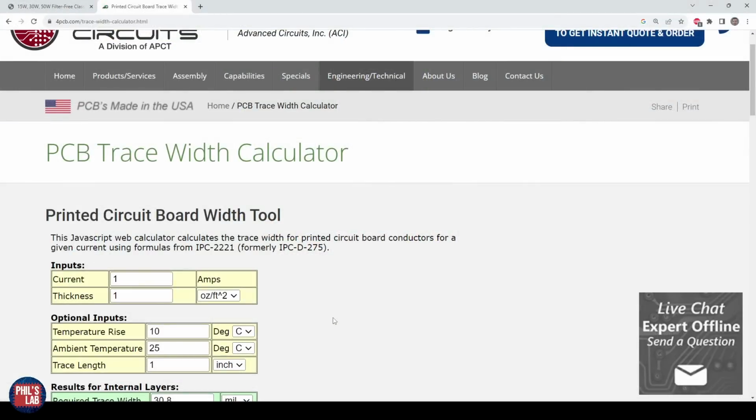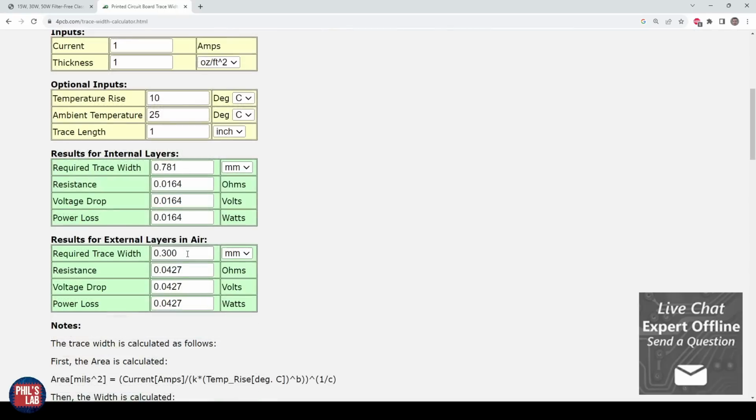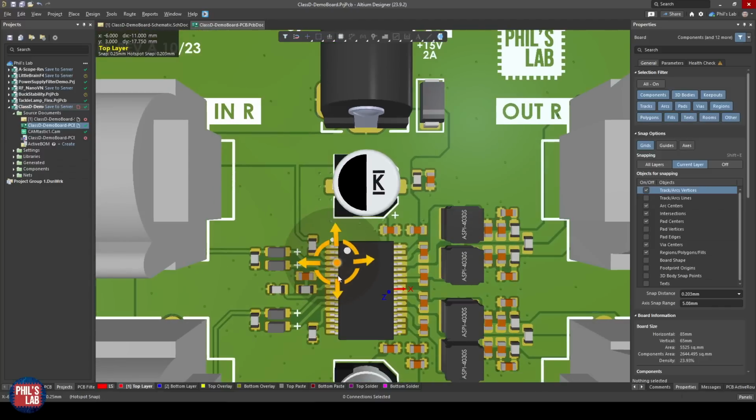As usual, I'd strongly recommend checking out an IPC-2221 calculator, which lets you calculate the required trace widths given expected currents, copper foil thicknesses, and temperature rises as well as ambient temperatures. However, it pays off to make your traces not incredibly large, but larger than what the calculator specifies, because this will reduce inductance and of course further reduce the DC resistance and improve power delivery.